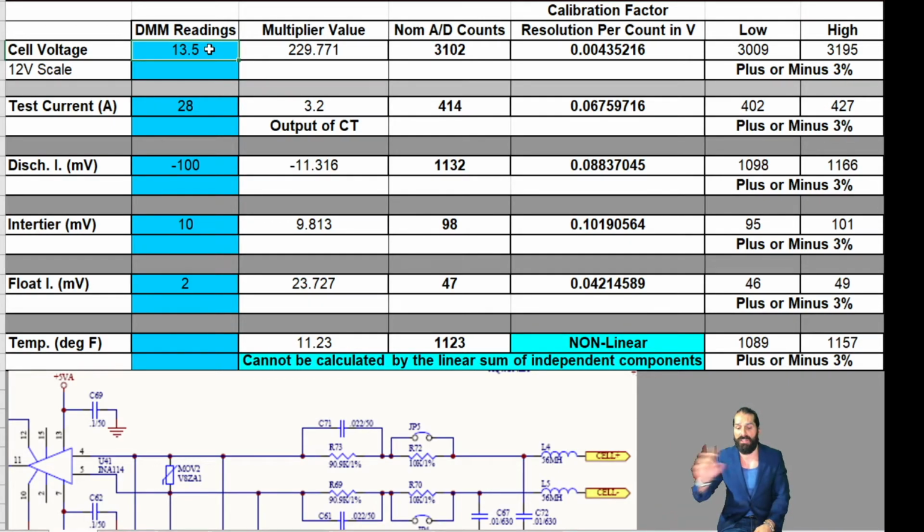But now look, when we change this, let's go down to 13.1 volts. See how that changes on the input there? It'll have the low and high side, but we use this to calibrate the system. If there's a high resistance on the input, you're going to incorrectly calibrate it. You're not going to have enough room on the top end of that ceiling for the system to move up and down.